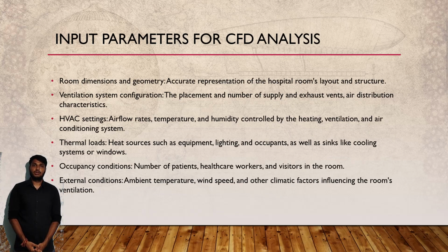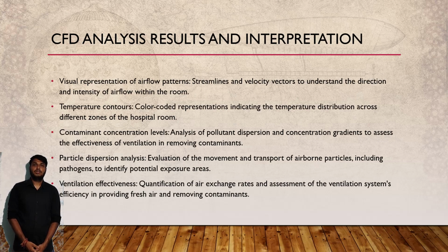Now let's talk about the input parameters for CFD analysis. To conduct accurate analysis, we consider various factors including room dimension and geometry, ventilation system configuration, HVAC settings, thermal loads, occupancy conditions, and external conditions. By simulating different scenarios and optimizing these parameters, we can gain valuable insights into the effectiveness of the ventilation system and identifying areas for improvement. Moving on to the CFD analysis result and interpretation.